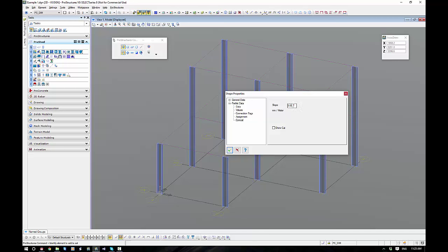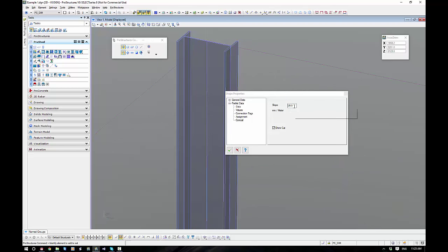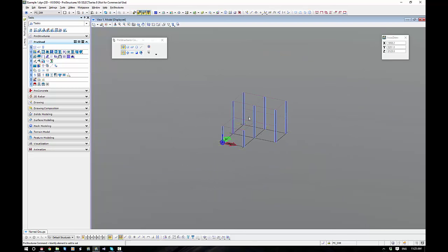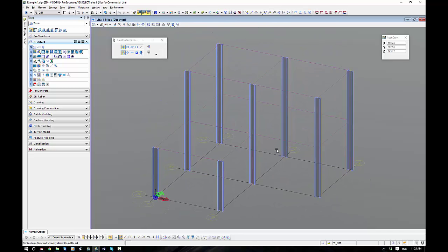The final thing, actually, while I'm here, let me just show you. I could actually make a tapered beam that's cut. Oh, I went a bit crazy here. Let's reduce that back to something a little bit more realistic. Let's go 20 mil taper. There we go. So you can see it's cut the beam. I need to go a bit more than that. 50. Just see if I can get that to work. So you can see you can actually have tapered beams and everything. Does a lovely job.